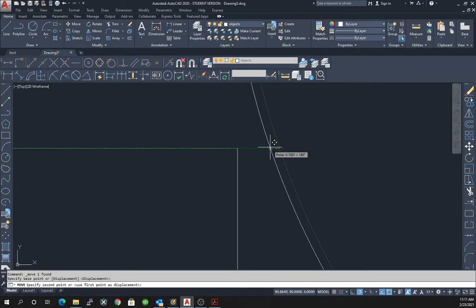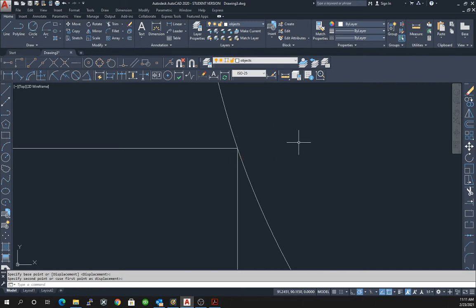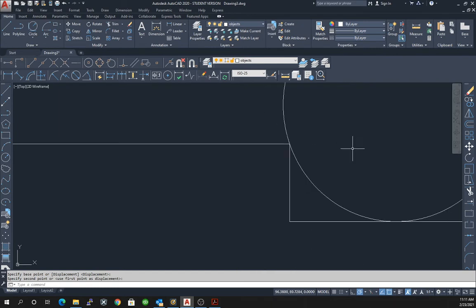And then all I do is I move that vertically until I get directly to the end point, to that intersection. Then I hit my mouse button again, and I've done the move properly. So now this circle has moved so that it's actually tangent here, and it makes contact to the end here.